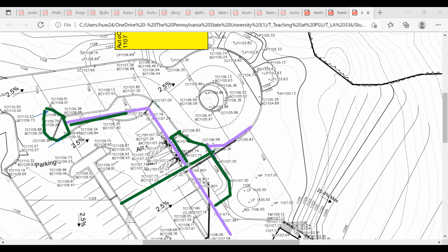I think we can cut through in roughly this location because this is roughly half of this drainage area, right? So that seems to be a good location to start your retention. And we don't need as much trench drain in this case. We will need curb cuts. Well, a short trench drain going through, and again, I would recommend putting the ADA over here.